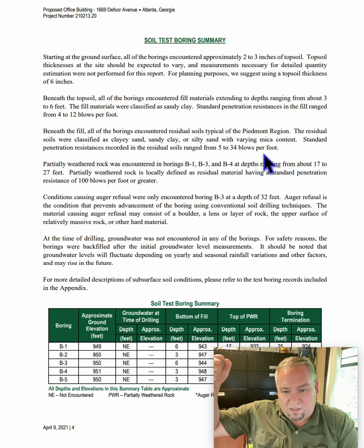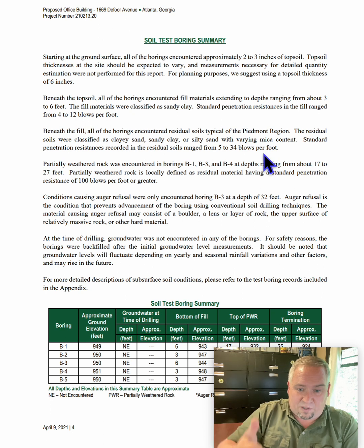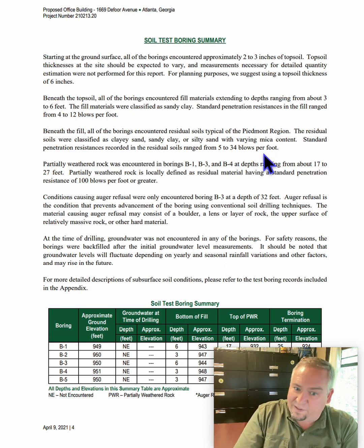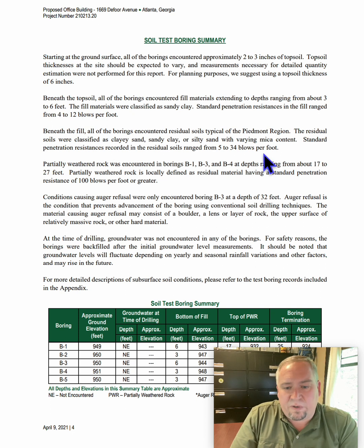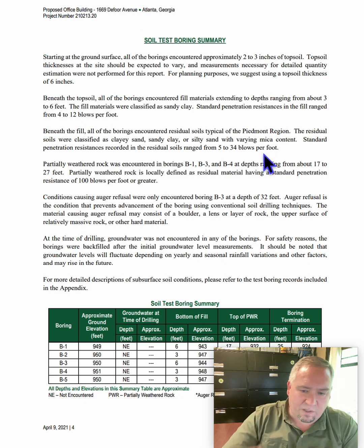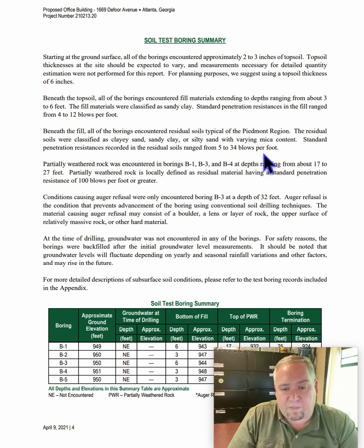So to get through this 1 foot of dirt here, it took me 15 blows. Okay, that's medium density. Or if it took 3 blows, like I'm in sand, and dook, dook, dook, and it went down a foot, that's soft stuff. So the blow count can tell you the density of the soil. And when you start excavating with an excavator and you're having to really work that thing, you're going to know that those blow counts are higher. And you can anticipate that.